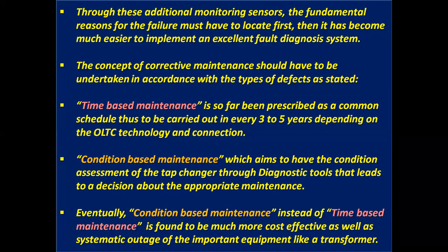Condition-based maintenance aims to have the condition assessment of the tap changer through diagnostic tools that lead to a decision about the appropriate maintenance technology. Eventually, condition-based maintenance instead of time-based maintenance is found to be much more cost-effective, as well as systematic outage of important equipment like a transformer.